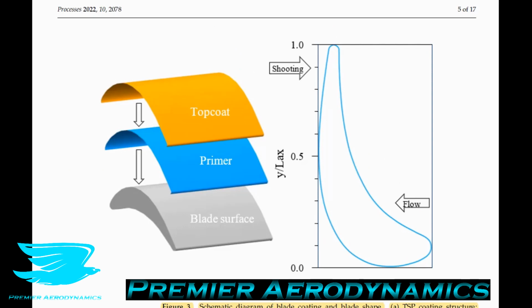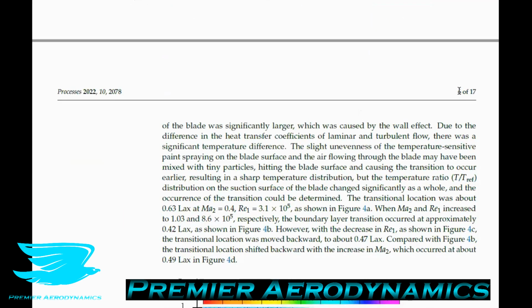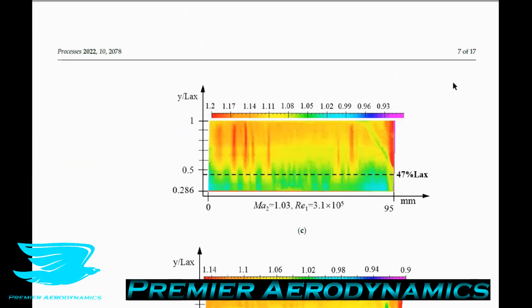To give you an idea of what it looks like, think of a hockey stick, but then you squash that corner a lot to make it more rounded, and that's very much what it looks like. It's a very cambered airfoil. It's fairly thick, and it's at like a 30-degree angle of attack. So it's very extreme.